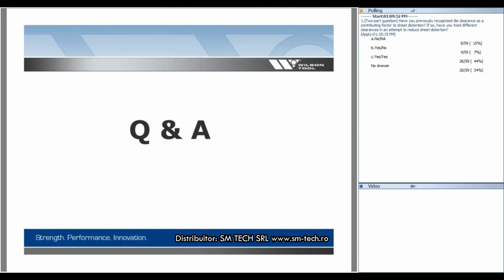An Amada has a P&F. The Trumpf can hold the material with a stripper at 25 tons of force as well. What's the difference? Actually, that's a good point. The Trumpf stripper, 25 tons, is for a piercing operation. The Amada P&F is dealing with the forming operations. So, a good thing, thank you for pointing that out. The P&F, pierce and form, is really dealing with a forming tool.